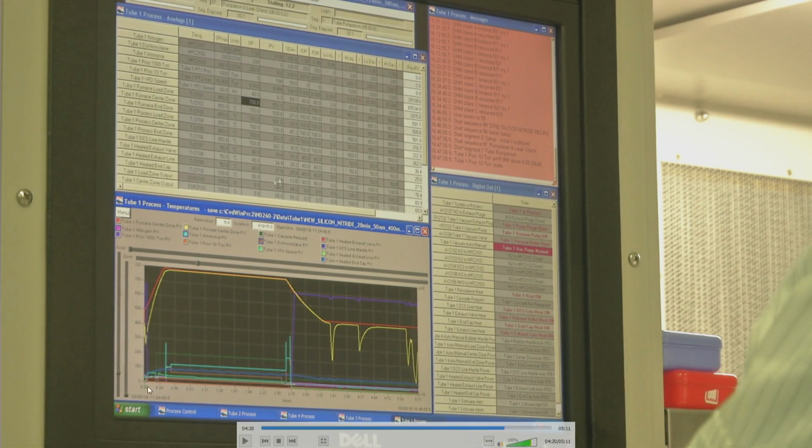Right? So when you look at the different color traces here, they are nothing but traces of different gases. If you stay at the deposition temperature, in this case about 750 or 760 degrees Celsius, this is where both your silane gas and nitrous oxide react and create silicon